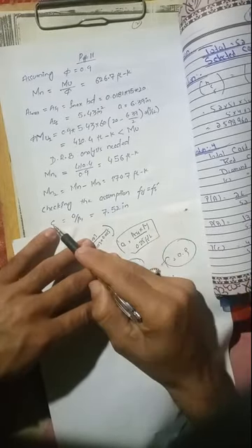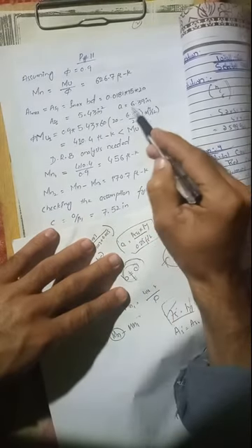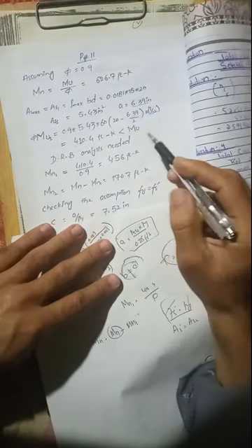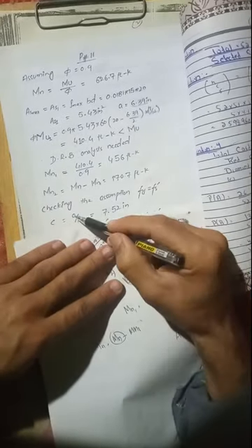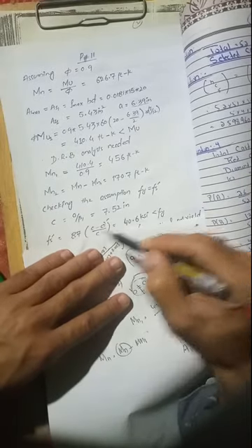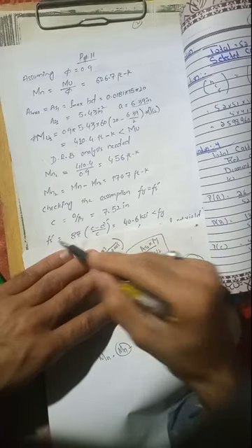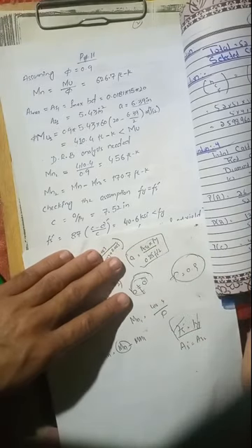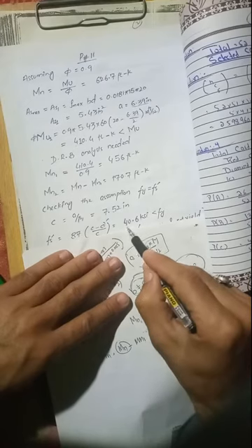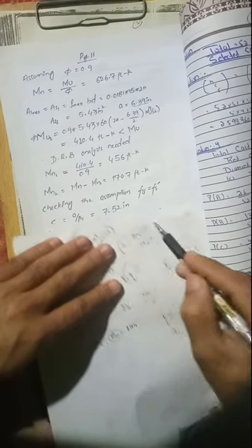All right, so let's say we are assuming fy equals fs prime. So calculate the c value, a divided by beta 1. You need the a value, and the a value is already calculated, this is 6.39 from this equation, right? You just divide it by beta 1, 0.85, and you get 7.52. Now check the fs prime value. I already explained this in those three lectures.